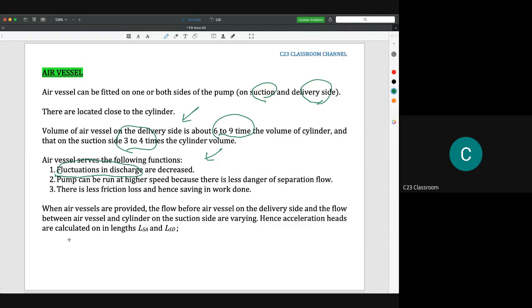As you know, previously I showed you the graph of flow rate. If it is single acting, it starts with the vacuum, then transfers water, then starts to vacuum and transfers water again. That means water can be transferred at certain points only, at certain times only. To overcome this problem, people will use a double acting piston pump.